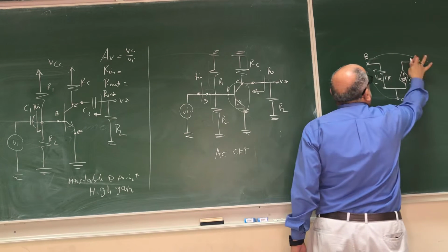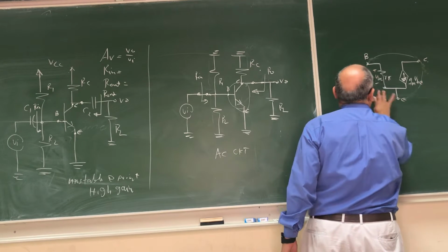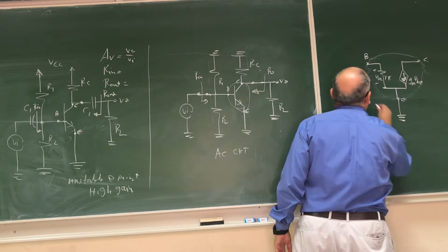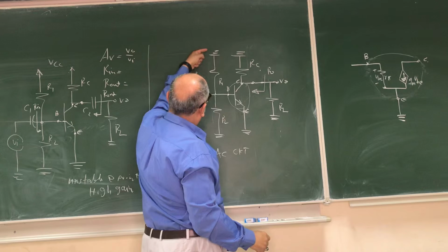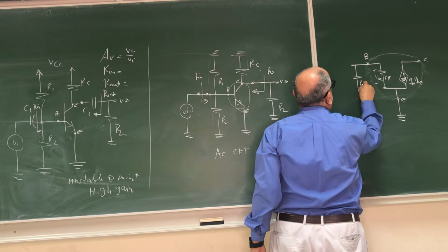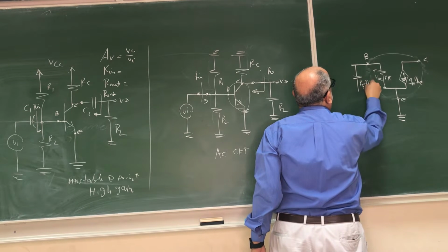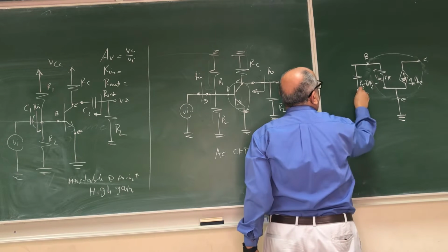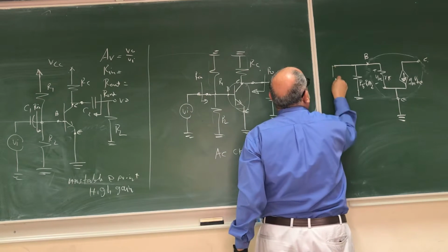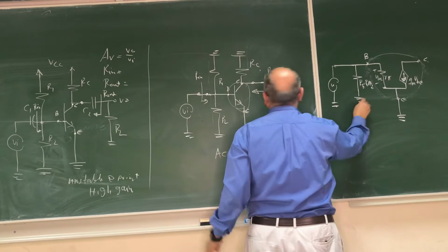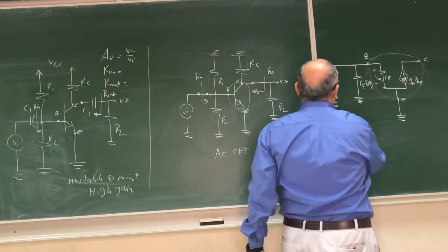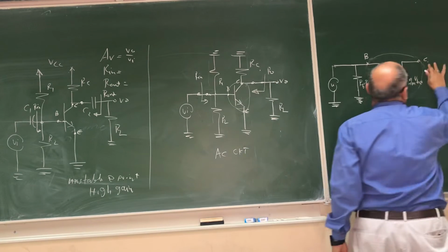Now, I have to connect now the rest of the circuit. So I'll start with the emitter. The emitter is grounded, so we ground it. Then from the base here, we have R1 and R2, they are in parallel, so we can call this combination RB equal to R1 parallel with R2, two resistors together here, right? Then we have here only the source, that is Vi, ground, we don't have an RS here. If there is RS, then we have to include it here. But RS will not be part of the input resistance, you have to keep this in mind.